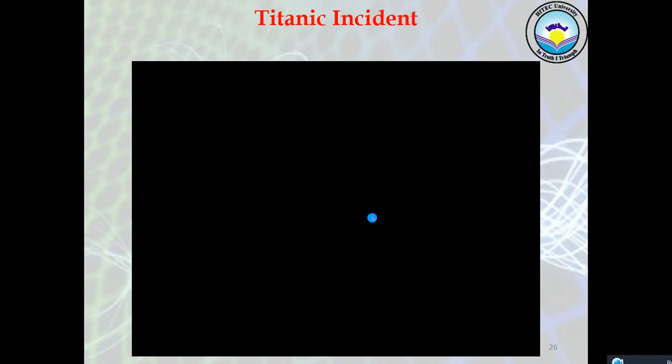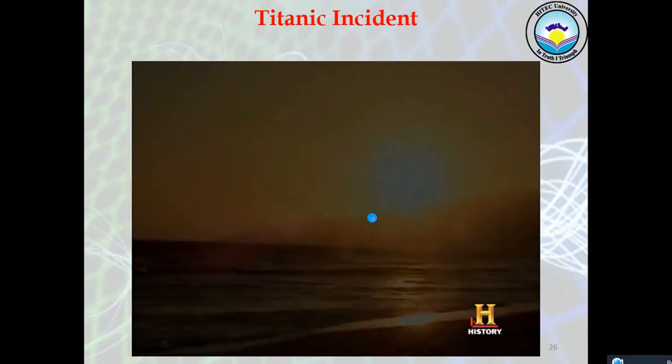So these kinds of disasters are interlinked with material failure. So we have seen the mechanical disaster was because of the steel failure. The grade of the steel used was showing brittle behavior at a frozen point, and when it got colder it was showing brittle behavior. So that's why the abrupt failure of material was because of the higher energy spike, and there was a ship strike with the